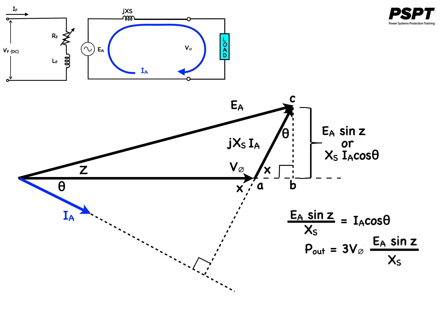Since the resistances are assumed to be 0, there are no electrical losses in this generator, and this equation is both the P conv and the P out. This equation shows that the power produced by a synchronous generator depends on the angle δ between Vφ and EA.